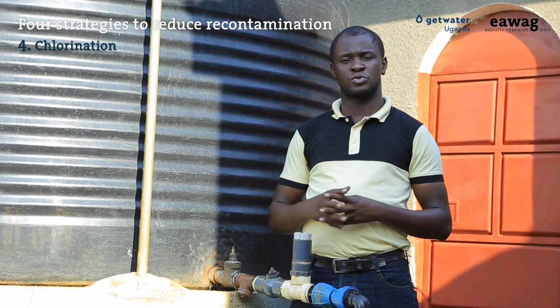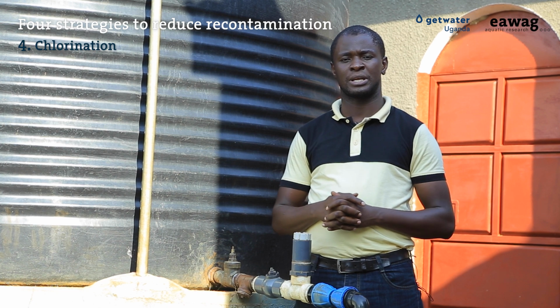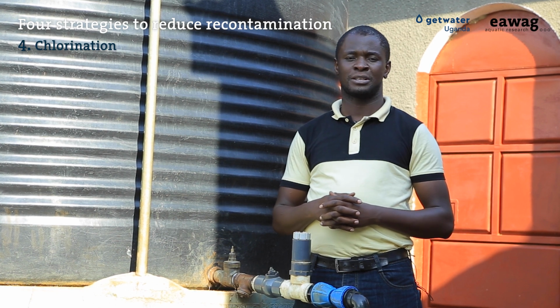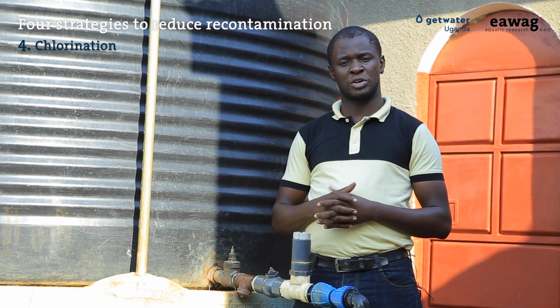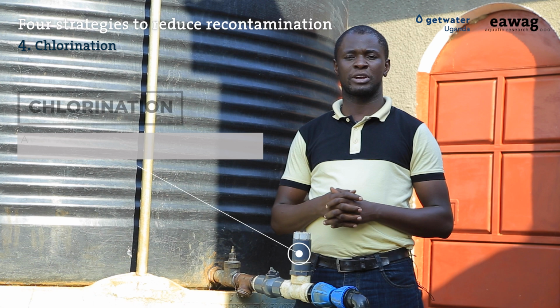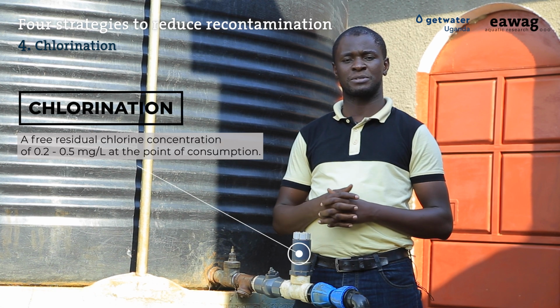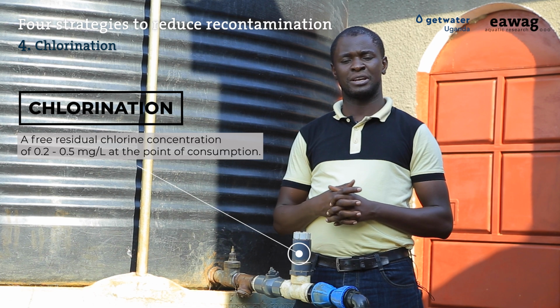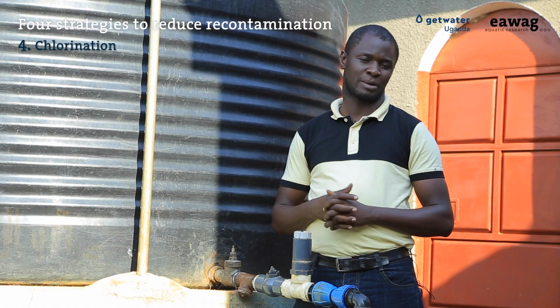The last mitigation strategy to reduce recontamination is chlorination. It is important to adapt the chlorine dosing to the local situation to achieve a free chlorine concentration of 0.2 to 0.5 milligrams per liter, as recommended by the World Health Organization for drinking water consumption.